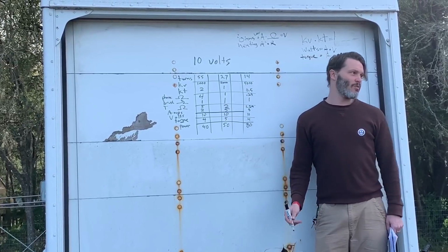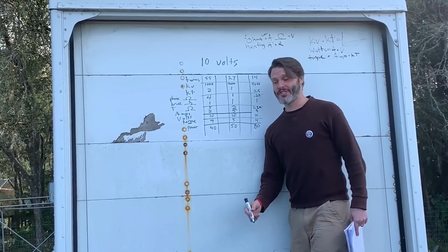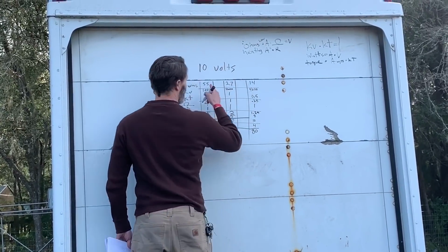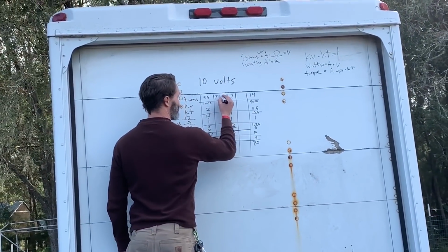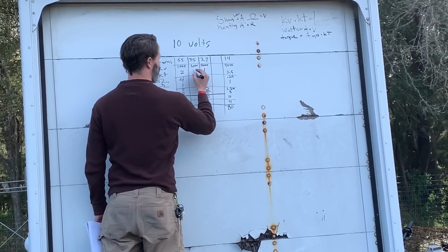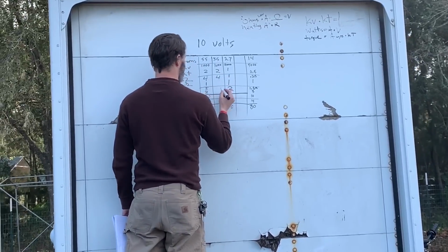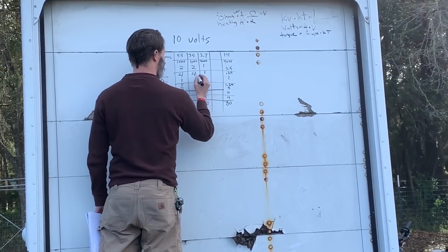Not everybody wants that. What if we doubled our voltage on that 55 turn motor? I haven't run the numbers, so I'm kind of interested to see what happens here. We are still a 55 turn motor. It is still 1,000 kV. Our torque constant has not changed. It is still 2 units. Our phase amps, it's all the same. Our phase ohms, our brush ohms, all the same.